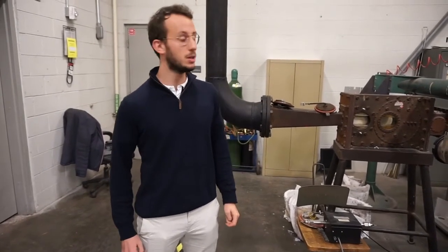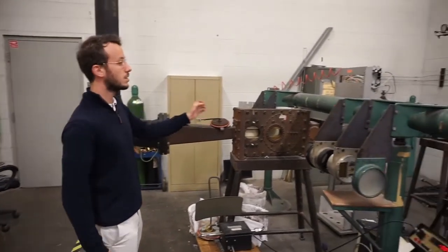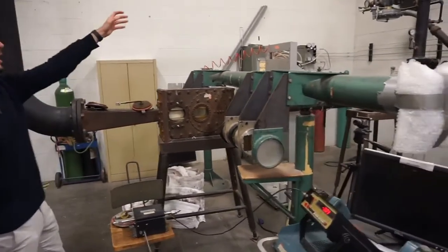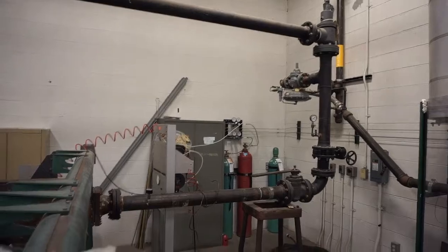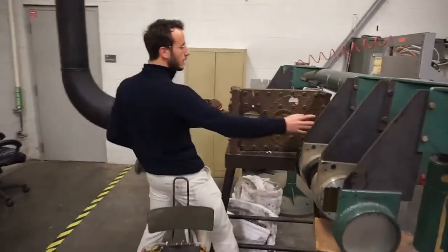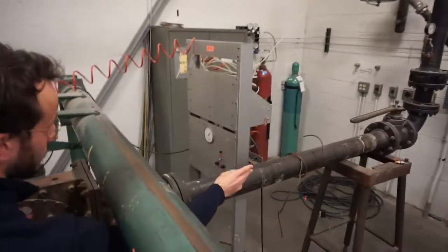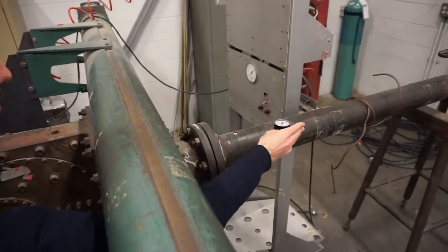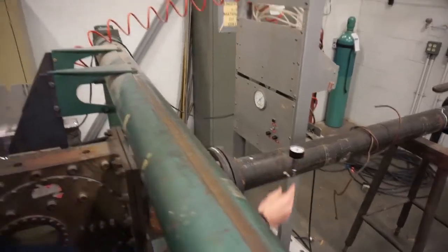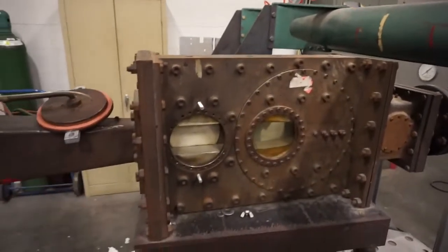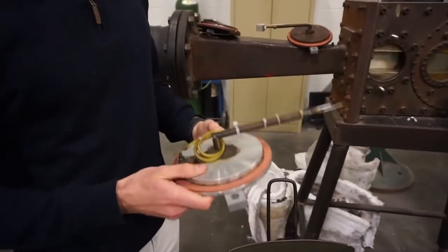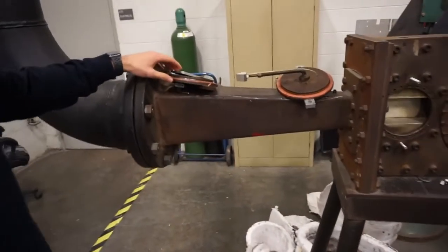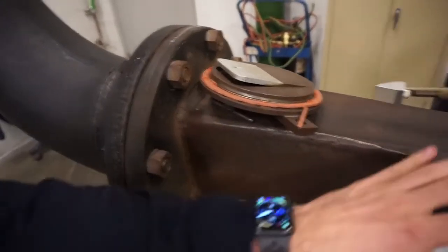In the second part of this lab, we'll use another supersonic tunnel, the blowdown tunnel right here. It's also connected to a high pressure supply in another part of the room. It gives pressure to the pipe right there, and we can control the pressure inside the blowdown tunnel by looking at the pressure gauge upstream. During the lab, we'll put 3 different plates, which consist of one pitot probe and static tap, one variable area diffuser right here, and one wedge.